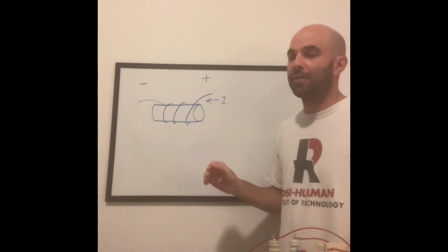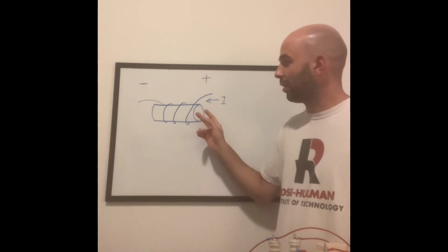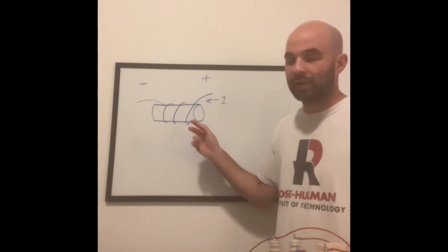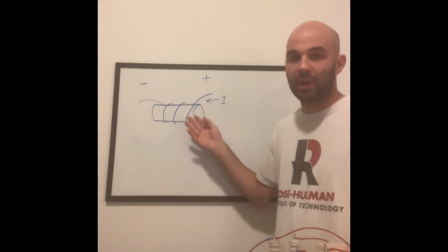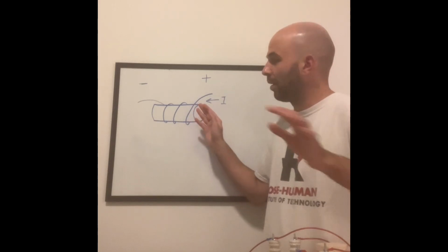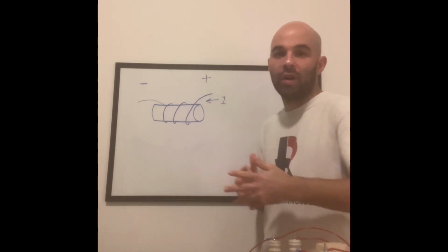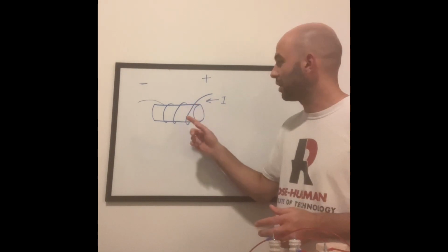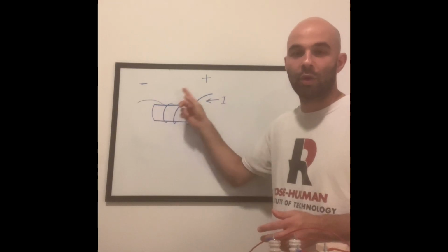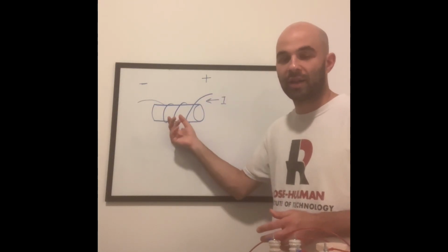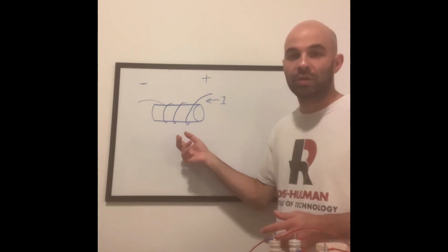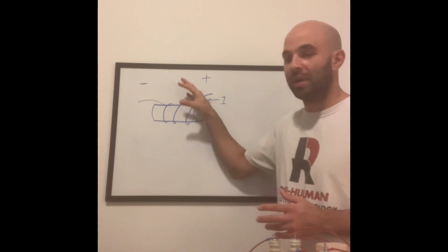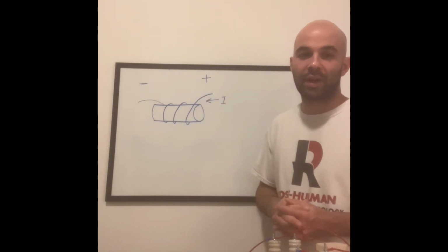And what happens is, if your potential gets too high and your voltage gradient turn to turn gets too large, your coil is basically going to start arcing over. So the turns in the middle part of your transformer are going to be losing energy. The energy is not going where you want it to go on the outputs of the coils, but is lost in the middle of the coil because your voltage gradient is too high and your arcing or bombardment is too strong due to the high electrostatic effects.